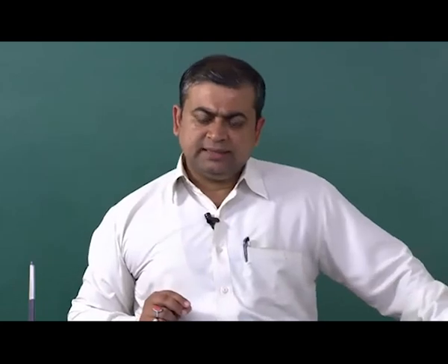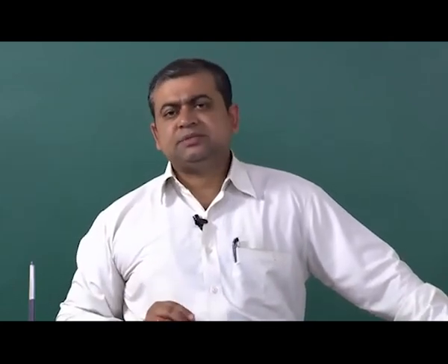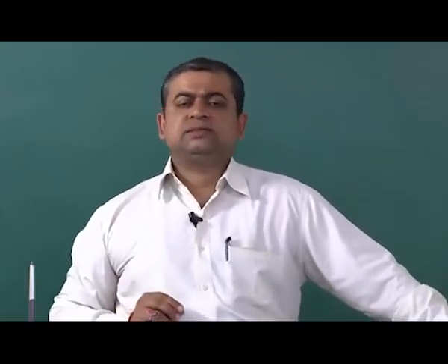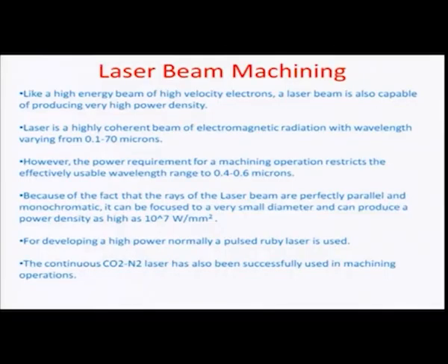So in order to investigate the laser beam machining process, one needs to really look into the fundamentals and the basics of laser. Laser, as we all know, is light amplification by stimulated emission of radiation, and let us look at some of the properties of what a laser beam is capable of. Just like a high energy beam of high velocity electrons, the laser beam is also capable of producing a very high power density locally on a surface. It is a highly coherent beam, as most of us know laser to be. It is electromagnetic radiation, and it has a wavelength which varies from about 0.1 to 70 microns.